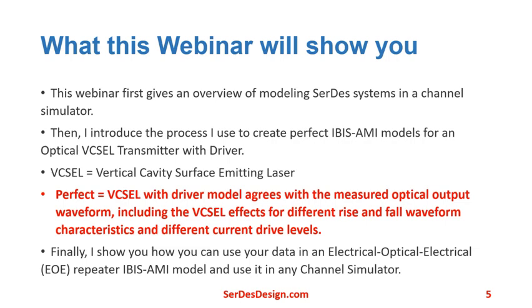Perfect means that the model for the VCSEL with driver agrees with the measured optical output waveform, including the VCSEL effects for different rise and fall waveform characteristics and different current drive levels. Finally, I show you how you can use your data in an electrical repeater IBIS-AMI model and use it in my free channel simulator or any channel simulator.